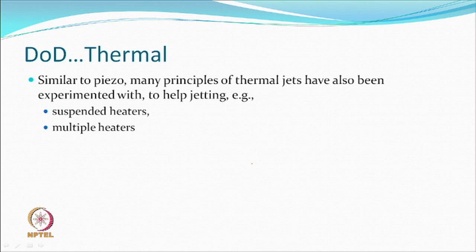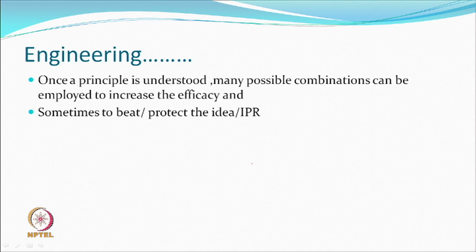So, thermal drop on demand, if we summarize, is similar to piezo. Many principles have been experimented with to help the jetting of the ink, like suspended heaters, multiple heaters. We have seen 2 heaters, but there could be multiple heaters, and one can work. So, the bottom line is that once a principle is understood, many possible combinations can be employed to increase the efficacy of the final product, which is a printer head.